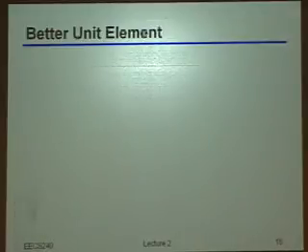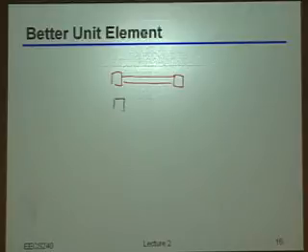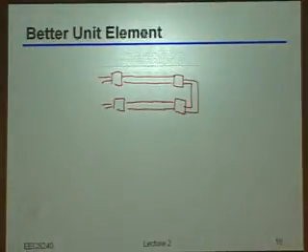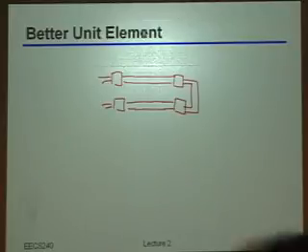Now let's redraw this again to make sure it's clear. If I wanted to do some resistor unit element, then my recommendation was to make it so that the unit element is always actually built out of two unit elements, where you make the connections like this, so that current is always flowing in both directions inside of the unit element. Then once you take that unit element and put more and more of them together, you never have this problem of messing up the current flow direction.